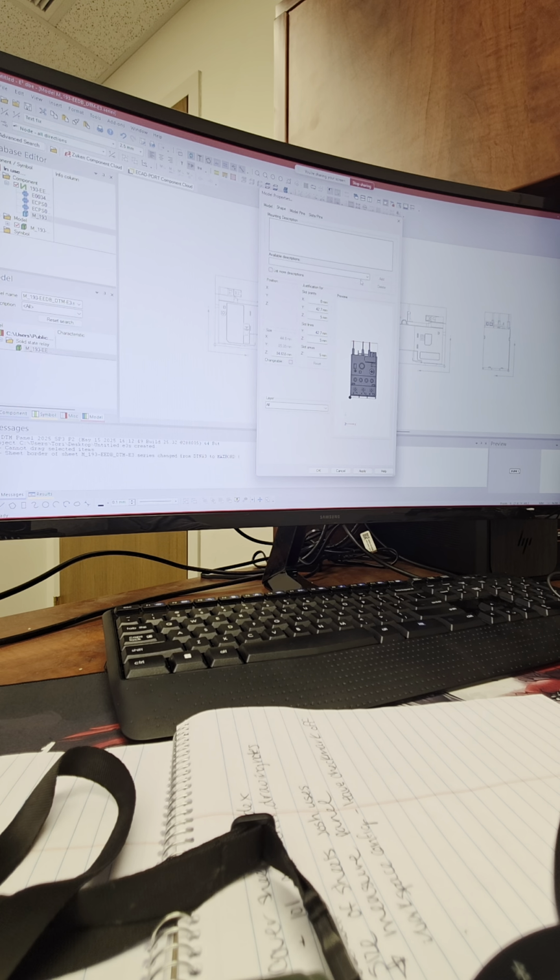If you use the drop-down menu once, depending if you used the previously TS35 will show up in this list. So like right now it is there. If you don't see anything, for example, the description wise, you'll just have to click on the list more descriptions, the little checkbox that you see there on the left if it doesn't show up. But if you use it once, it will come back here next time you search for it. So click on add to actually make this the default one, default mounting description. That's all we need to do with this guy. Click apply and OK.